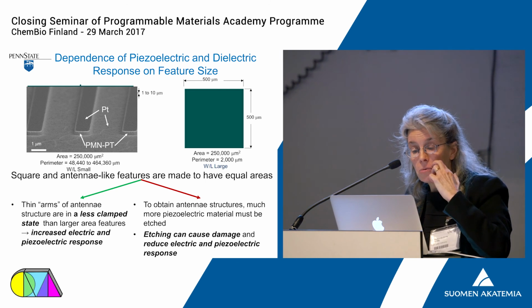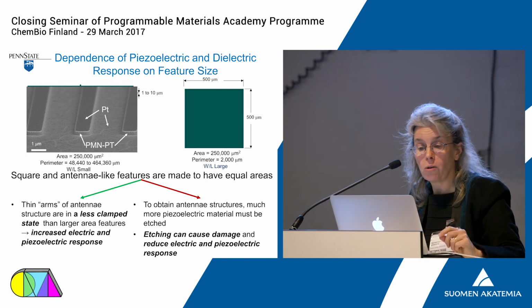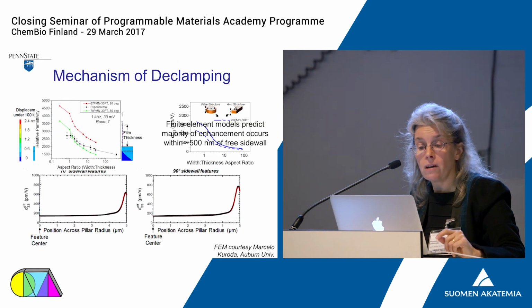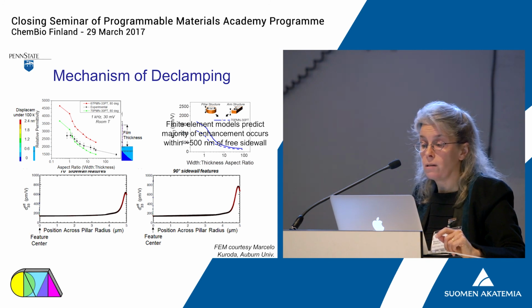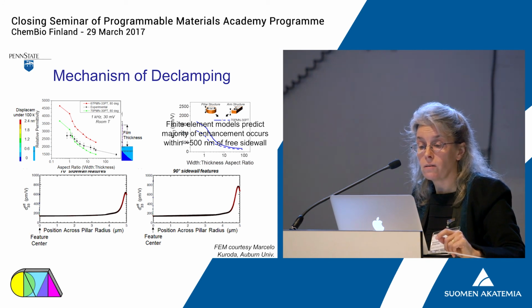And so we learned how to reactive ion etch devices. I show here ones that are about a micron in arm size. We've gone down to about 1/10 of a micron in arm size. And what we find is here's the measured data compared to what we would have predicted from a finite element model. We, in fact, can achieve relatively good improvements in the properties as we laterally scale the devices.